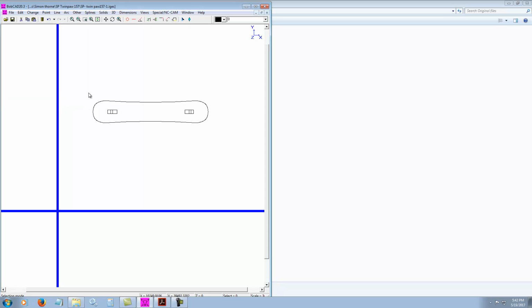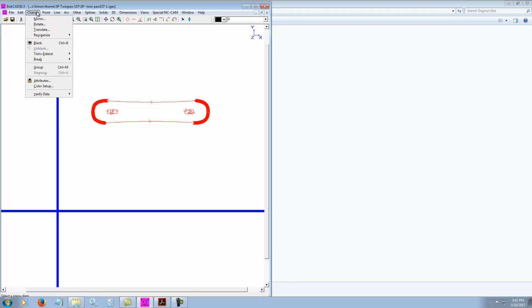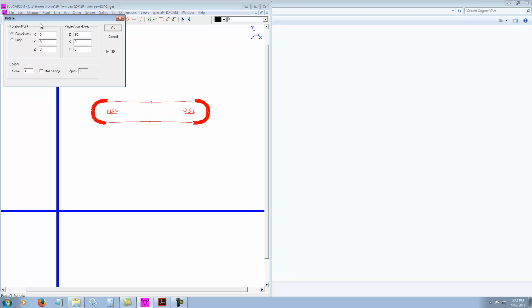I'm going to then click and drag this whole file so everything in the file is selected, and I'm also going to rotate it counterclockwise. So I'm going to choose the rotate command because it also can scale at the same time, and I can kill two birds with one stone. So I'm going to rotate it. In the scale dialog, I'm going to paste in, Control V to paste it in, or right click, edit, paste. 0.39, that number from the calculator is there.